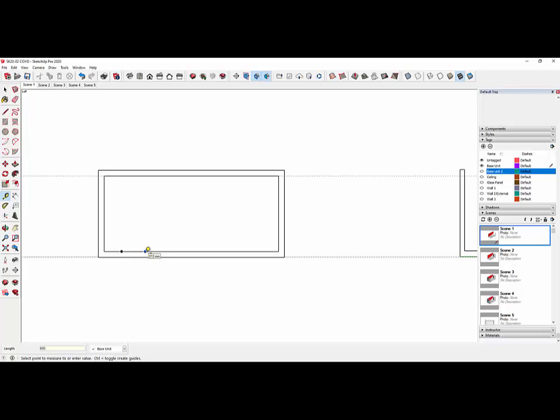So 600 along, left click, you see the marker pointers there. We can create a guideline. Just pull it beyond. Let's just drag another one across 600. So we can work our way all the way through the elevation itself, or we can just create one, cut it out, and then create a new wall and insert it. So we have various ways of working, but the use of the tape measure tool is a very good method of working.